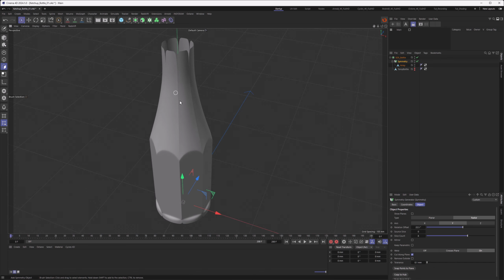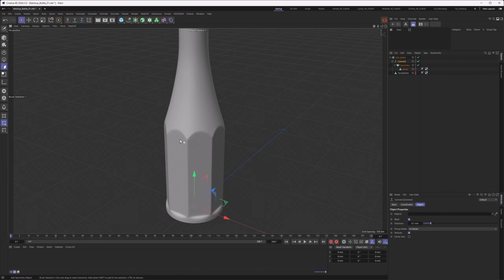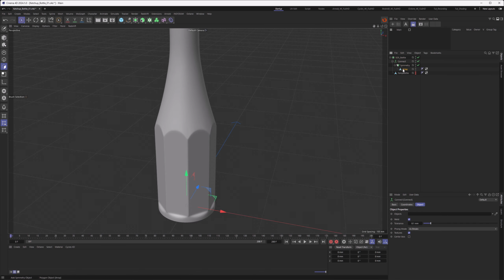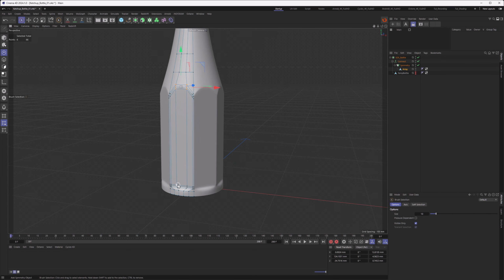Also, if I turn on the SDS, you can see every one of those pieces is singular. So to mitigate that, what I can do is go and add a connect object, and this will connect all the objects together. So now we can go in here on one of those instances and then tinker around with one and have a look at what is the overall effect on the object.